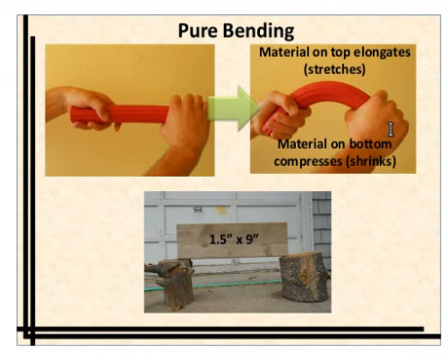It's also worth noting that you never really get a beam that's in pure bending. It's kind of a theoretical concept, but you don't have to worry about that too much right now. Anytime you apply a load, for instance, if you were to apply a force here on the beam, there would be some bending stresses induced in the beam. And what we're going to talk about is going to give you a conceptual idea of what happens when you apply that load.